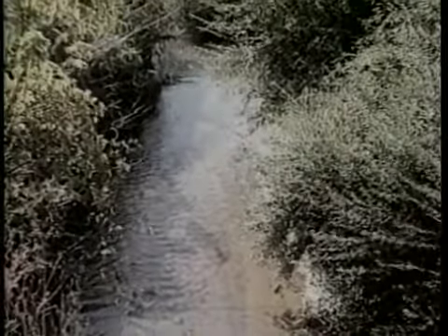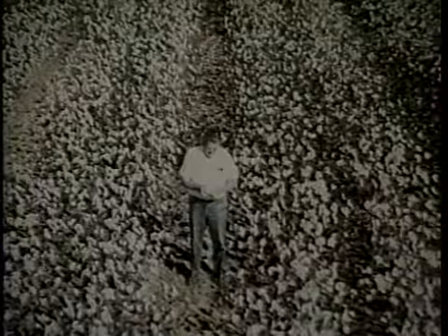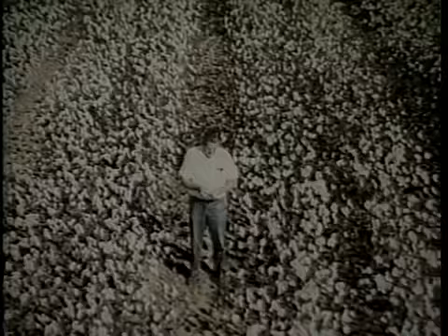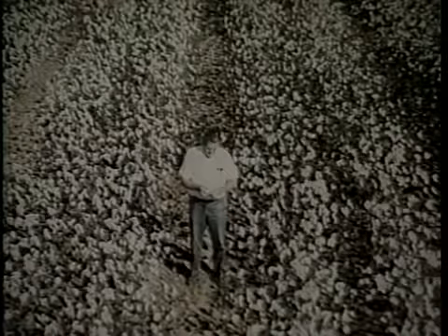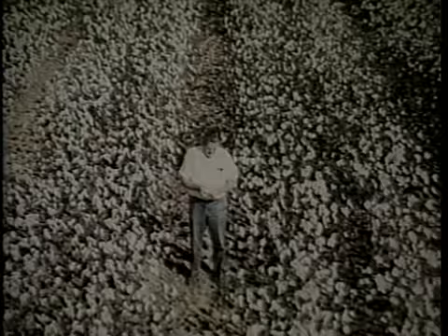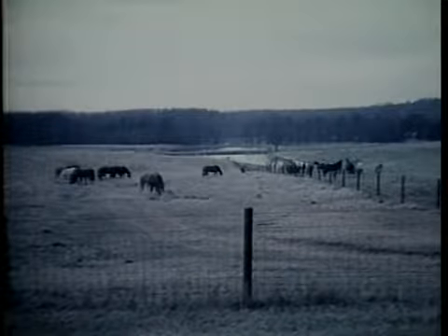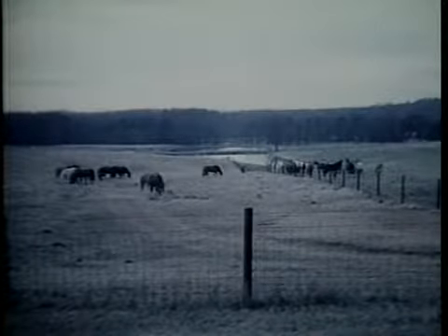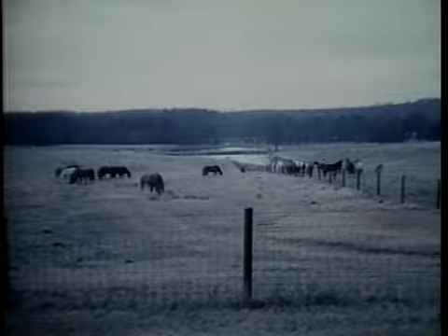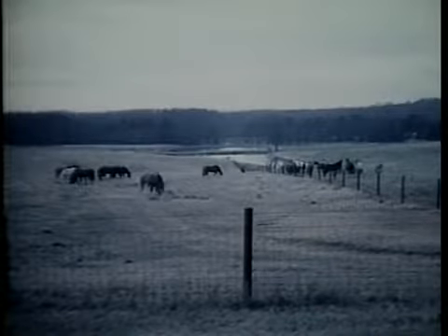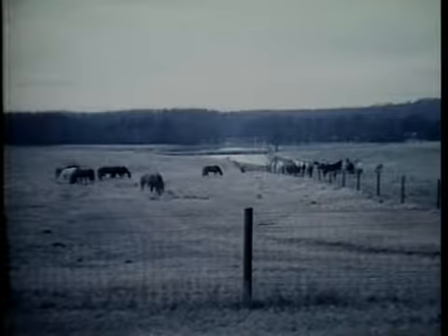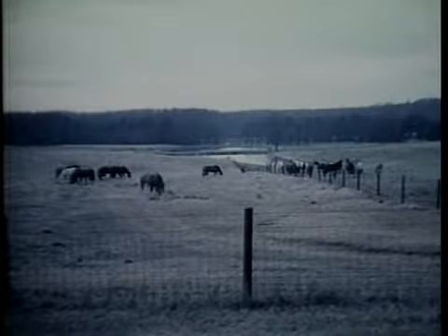Since the water quality of the stream is determined by the geology of its drainage basin or emerging springs from underground, quality varies considerably from stream to stream. For example, streams located in agricultural areas may receive drainage from fields which are treated with insecticides and herbicides. Streams receiving water from areas where livestock are held may contain high levels of organic materials such as manure, which may adversely affect water quality. However, well-managed drainage basins may add beneficial ions to the water, such as calcium and carbonate.